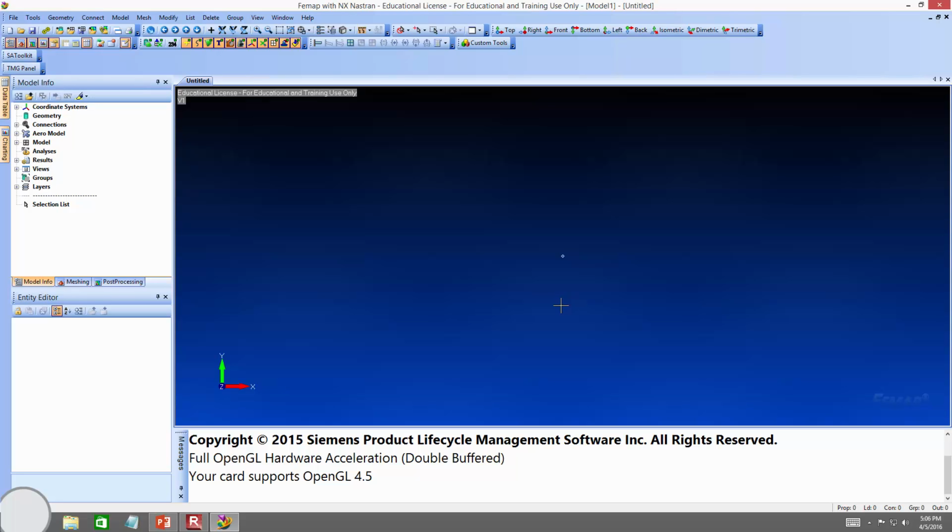All right, sound good? All right, so let's look at our problem. We're going to start off looking at this truss. And I'm going to do my best to keep with the numbering scheme that you see here so that you all have an idea of what's going on. So you notice this truss has 6 joints. Real quick, before we apply boundary conditions, how big is the stiffness matrix? See if y'all remember. What's that? All right, 6 by 6, because it's a truss.